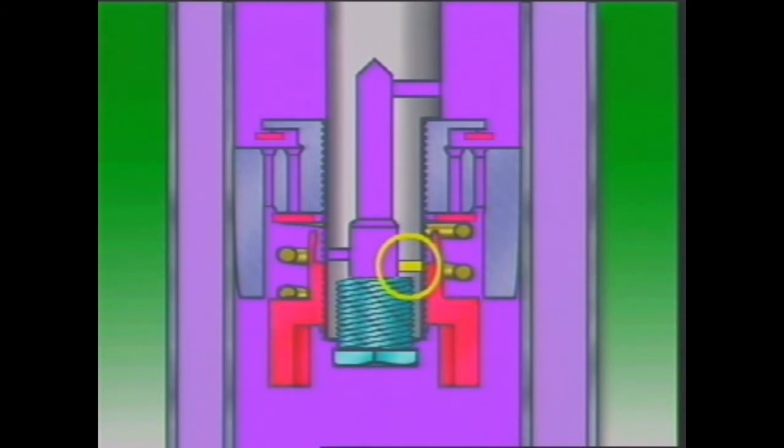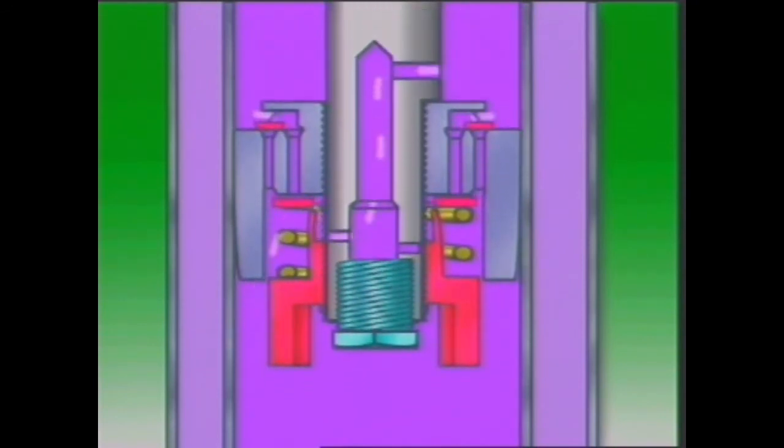Closing some of the orifices and increasing the spring force applied to the valves makes it harder for fluid to flow through the piston. This increases the dampening effect of the shock absorber.